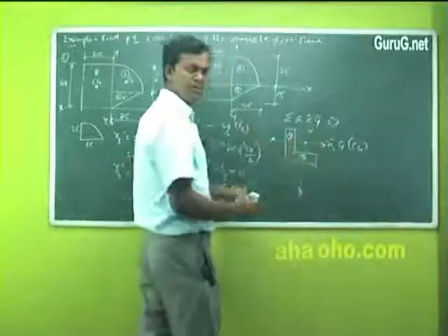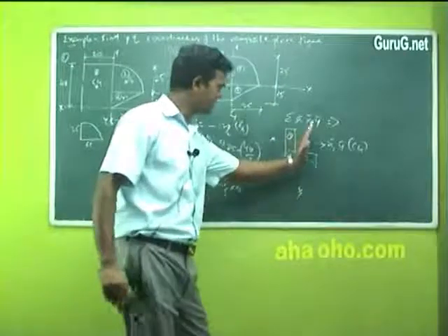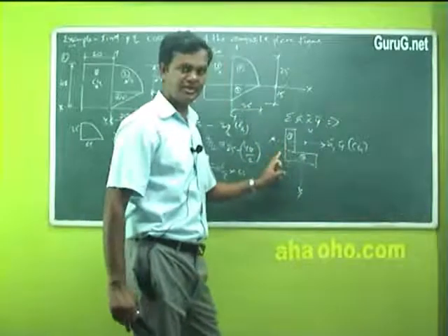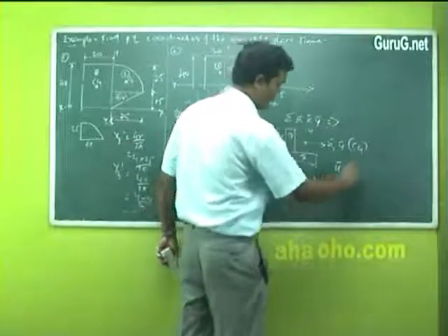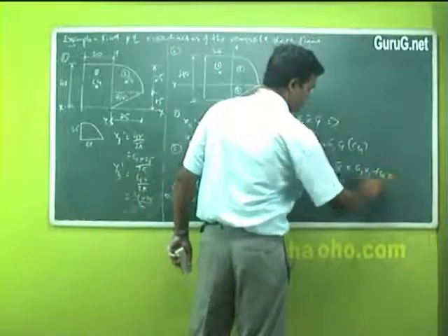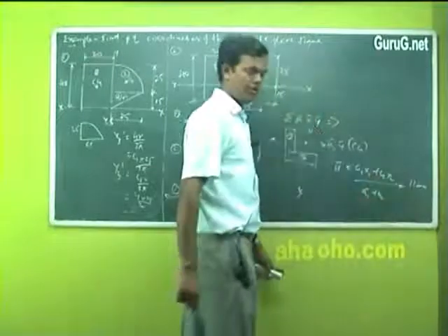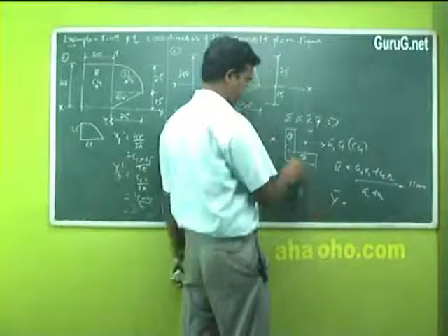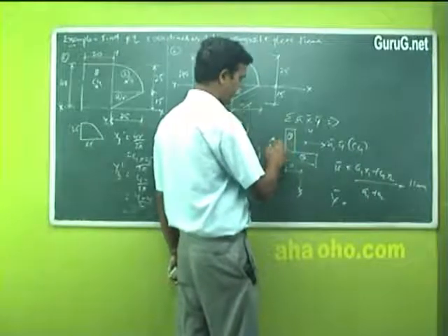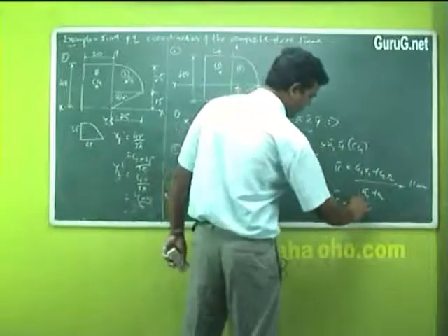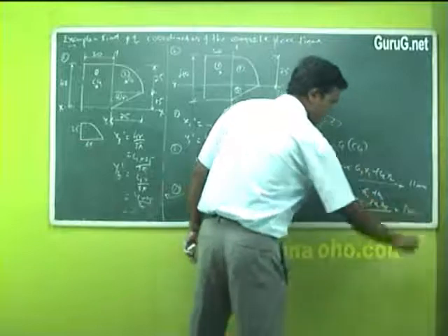From yy and xx, based on this sketch, suppose this is rectangle number 1, and half of this rectangle is to the left side of yy, which means whatever coordinates I fix here will be negative. For example, when my x bar value after solving a1 x1 plus a2 x2 by a1 plus a2 comes to, suppose, 11 millimeter. And y bar, by a1 y1 plus a2 y2 by a1 plus a2, these formulas we have seen already, comes to, suppose, 12 millimeter, whatever it is.